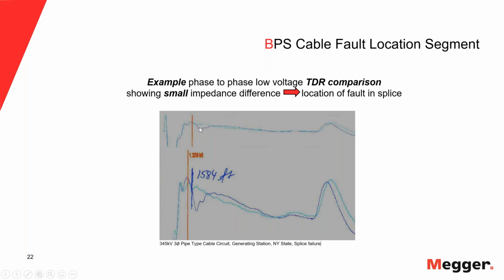So when I did this phase comparison, you can see the green line and the purple line, right? And you see clearly there is a difference. And so the one is lower impedance than the other one. The other one is pretty straight, so it probably has no problem. But the blue one certainly has a problem because it's not supposed to have a different impedance here.